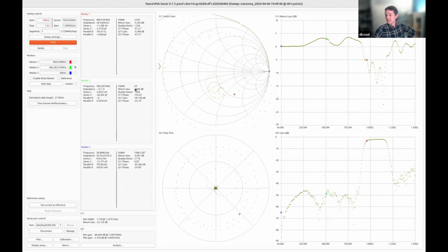That's not a correct result, which is why it's saying VSWR infinite, actually. This measurement, I've clearly bent the cables too much. The calibration is no longer valid. I should have gotten a filter that was in the better range of where this can actually measure well. The phase is clearly incorrect. We do not have gain here. It's a filter. It's not active. There's no way we could be getting more power returned than we're sending out. So this forward plot, I believe, the backwards plot is making a point that I wasn't expecting. I was expecting that to be below the line at least, but the punchline is you will get power reflected back.